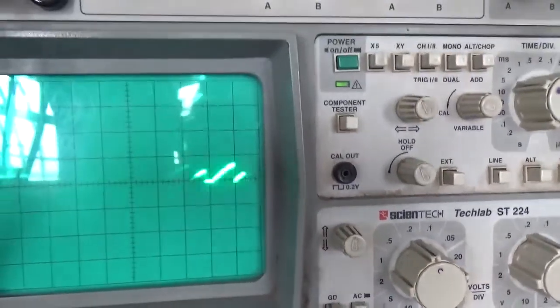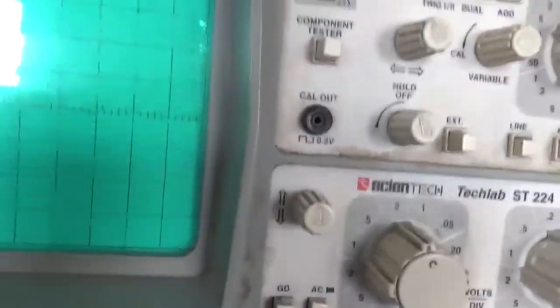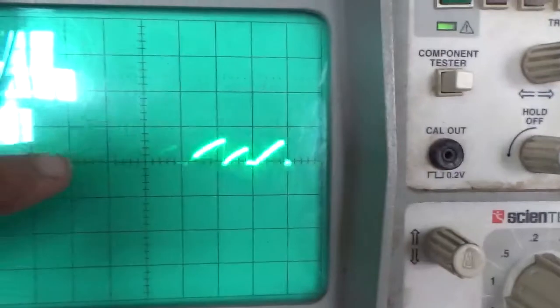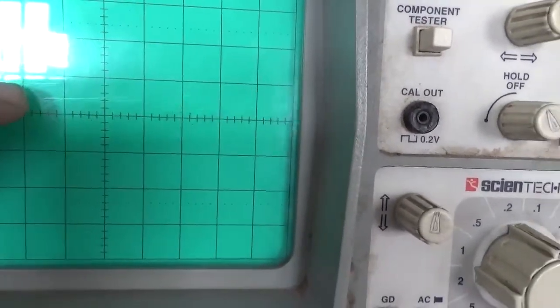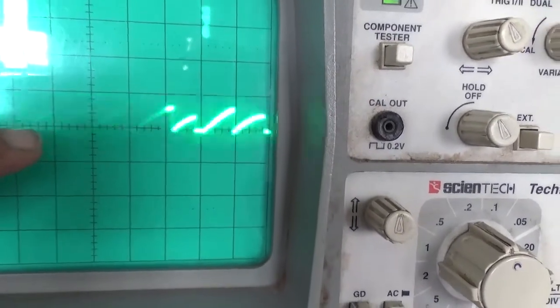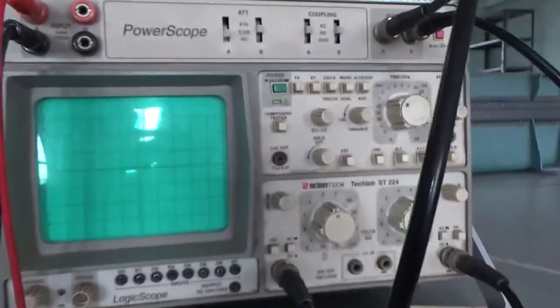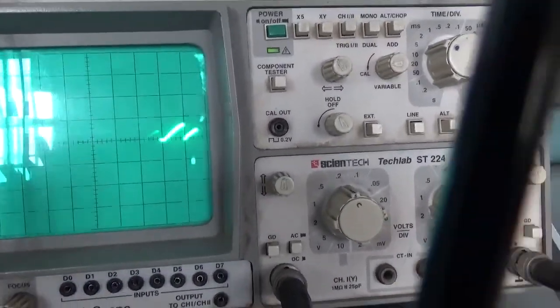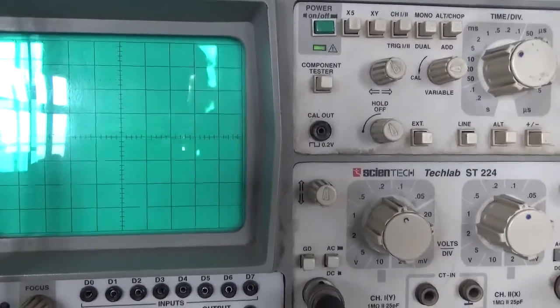This is the peak point, and this is the valley point. When the capacitor reaches the peak voltage, UJT turns on. When the capacitor reaches the valley voltage, UJT turns off. It's not necessary that you will get this many charging and discharging cycles in 180 degrees. That depends upon your resistance value.